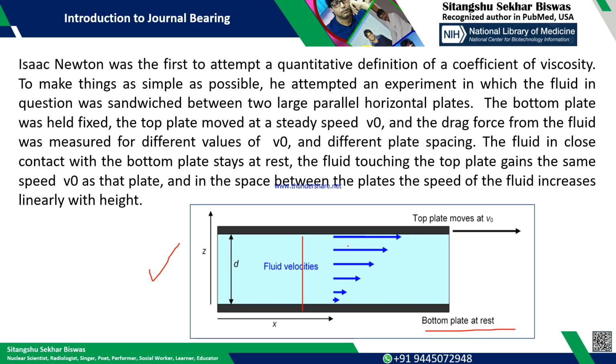What he observed was that the liquid which is just sticking to the inner surface of the top plate flows with a velocity at most equal to the velocity at which the top plate is moving, and slowly, as you go away from the top plate, the velocity starts to reduce. At the bottom plate, which is at rest, there is no liquid velocity.